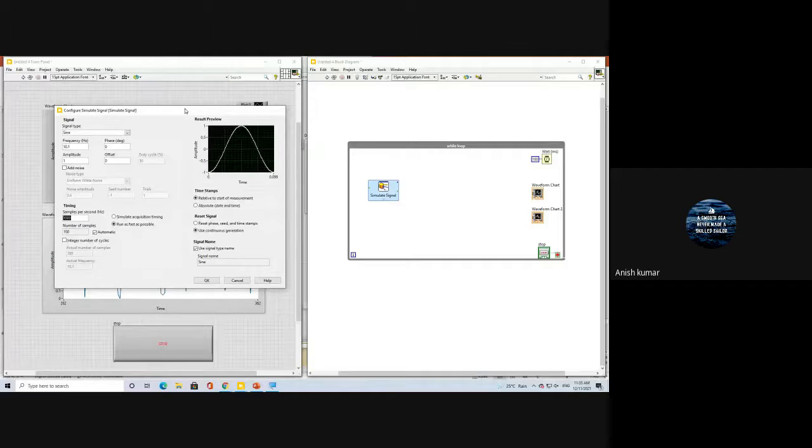Then message frequency. So this is message frequency and this is sampling frequency, right? What the Nyquist theorem is stating is that if you are taking a sample from the signal, and your sampling frequency is less than the message frequency, less than 10, this is not satisfying to reconstruct the original signal. So it is not possible.